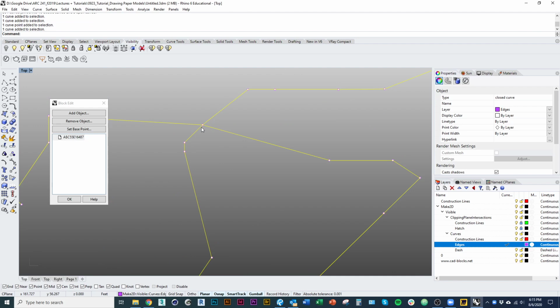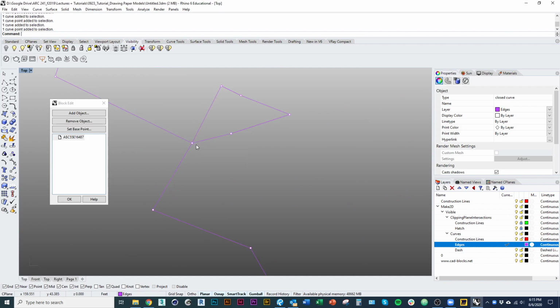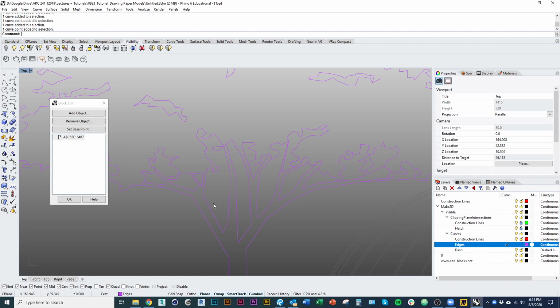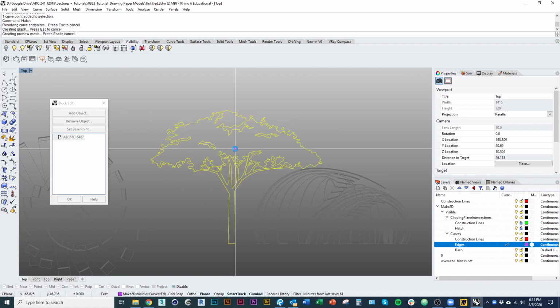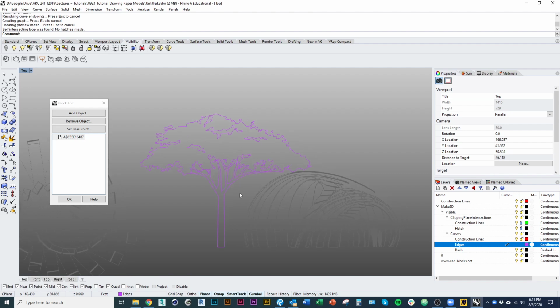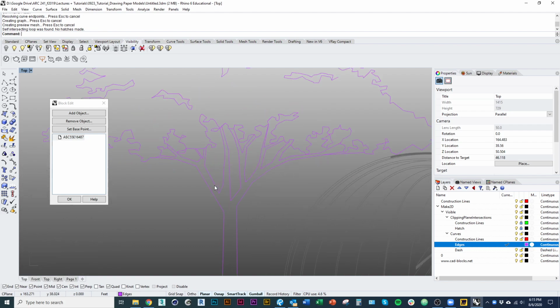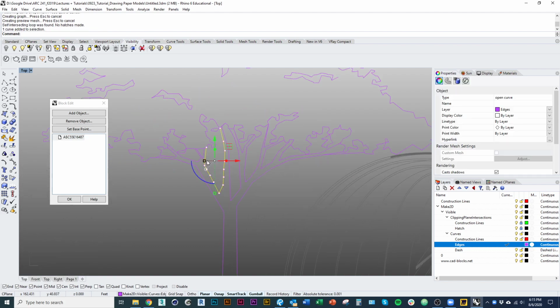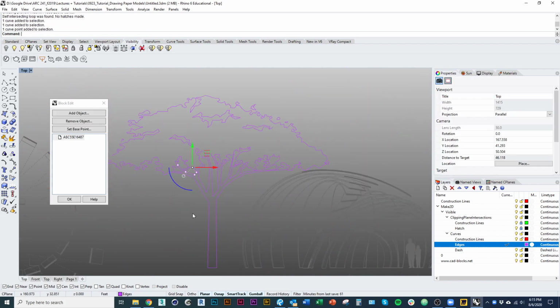so this is where we would have what's called a self-intersecting line, where there's a line crossing over itself, or making a kind of figure eight. So we want to avoid that. That'll confuse Rhino. Let's see if we can hatch it now. Still no. Yeah, I would just not spend a ton of time trying to fix it up. You could go through and fix every single line and make sure that you have clean outlines in between things, but it's just not going to be worth your time.